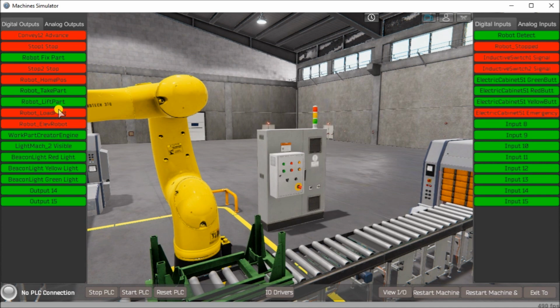Now this step is where you're going to spend most of your time programming. Understanding everything about the operation will save you time. It will help prevent you from continuously rewriting the PLC program logic. Knowing all the answers up front is vital in the development of the PLC program. So in order to facilitate this particular one, we're writing a sequence table.